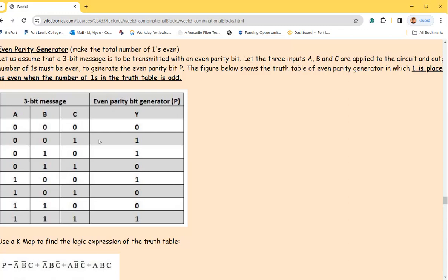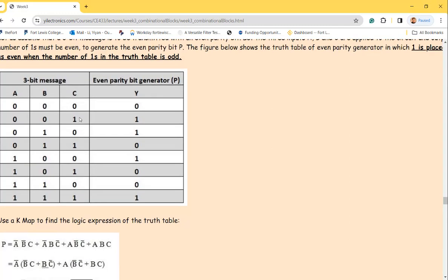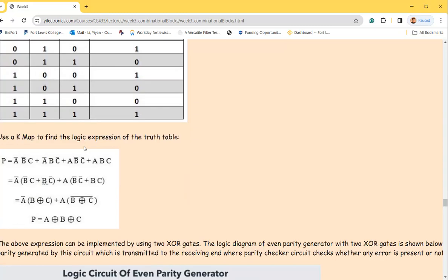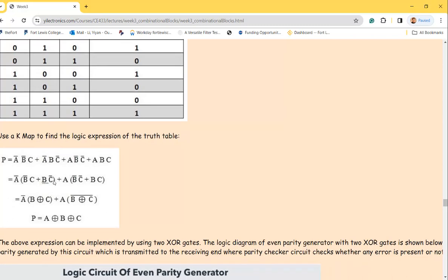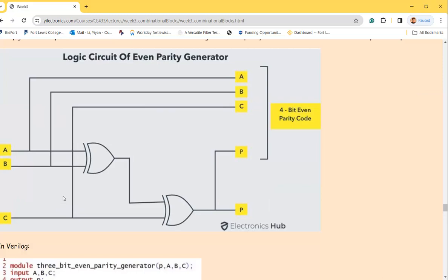And if you think about the logic, it's fairly simple. It's just combinational logic. You can put all the inputs and outputs in the truth table, because you know what the inputs are and what outputs you need for each input as a parity generator, right? So the parity generator is generating a parity bit. So you have 0, 0, 0, you just need a 0. You have 0, 0, 1, you need a 1. So on and so forth. You can easily fill up the truth table. And from the truth table, you can convert it into a logic function. Right, that's a schematic of it.